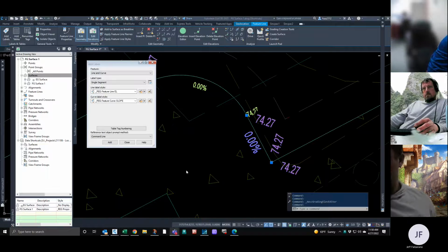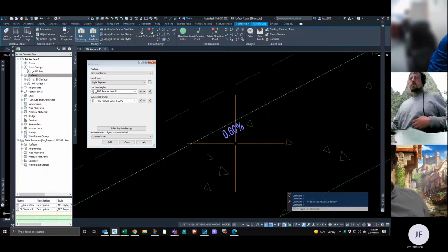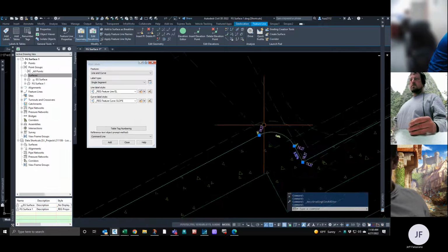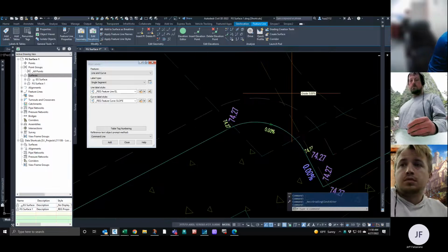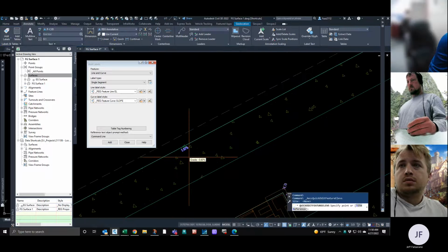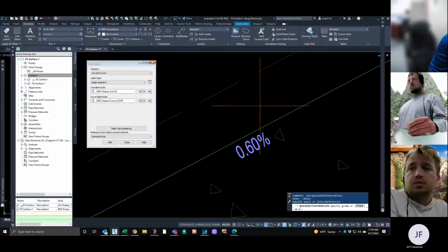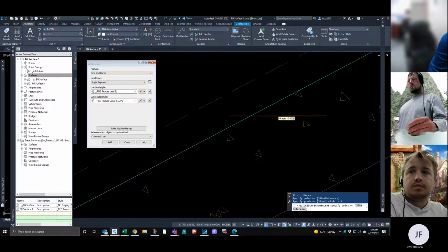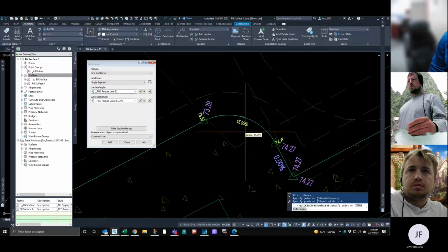If you pan to the left, can we see what the slope over there is doing? I think I might have that going the wrong way when I told you. So that's 6% uphill to the right, right? Is that what that says? Yep. Yeah, sorry, it should be 6% the other direction. Okay, that's an easy fix. So we go back to here. Hover over this slope. Click on it, do a minus 0.6. And that changes this elevation, changes this grade in between these two, and this curve.